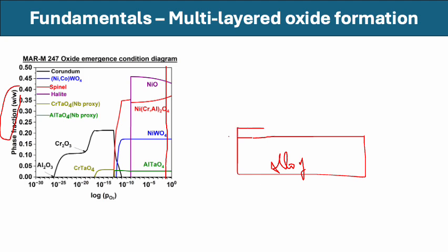So once that layer forms, let's say we'll use a different color for the oxide. So let's say this forms purple color oxide. Even though multiple oxides are favorable, you might have some embedded oxide particles inside here, but predominantly this. So let's say this is the oxide scale that has formed, which is the nickel chromium spinel oxide.